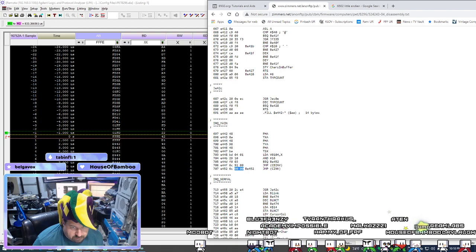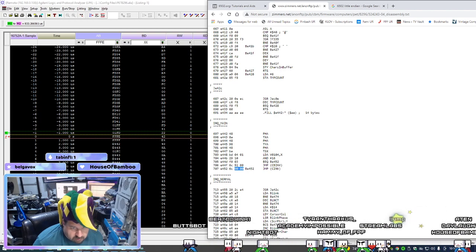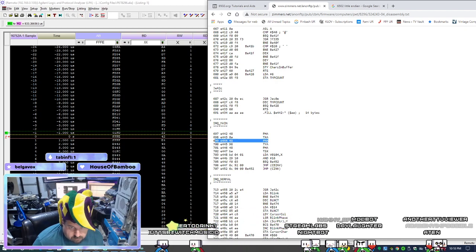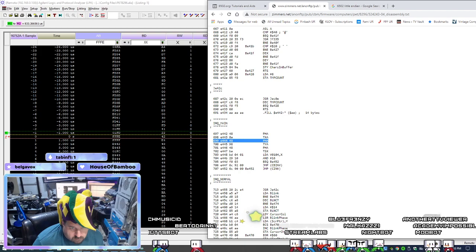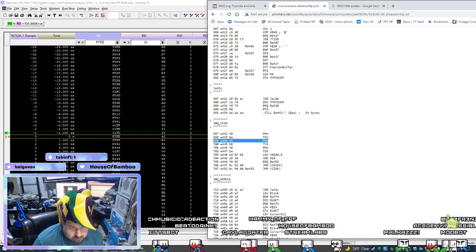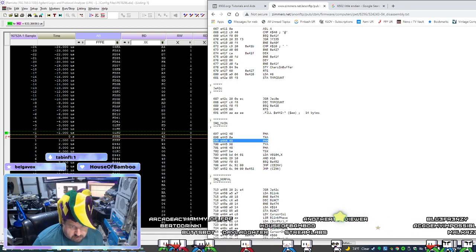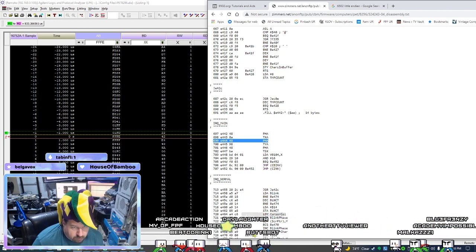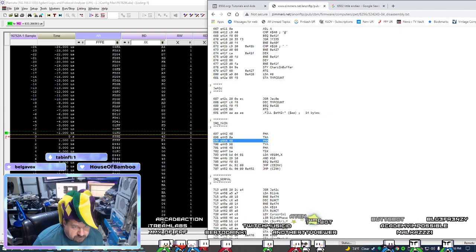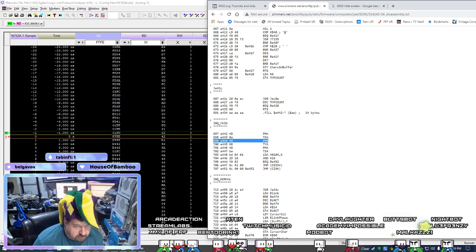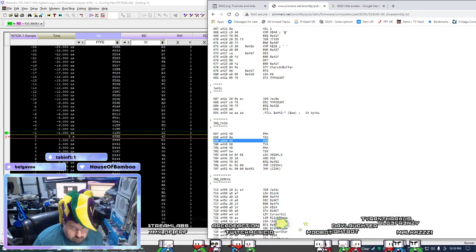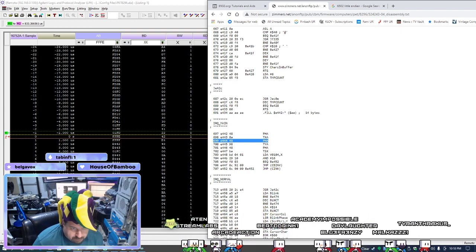You see 4A, 4A, 8A, 8A, and then this is the actual executing that opcode, so it's going to memory address 01FC00. I don't even know what's at that address because it's booted at F. So nothing right now. RAM is not initialized. So why it's screwing with that, I don't know.